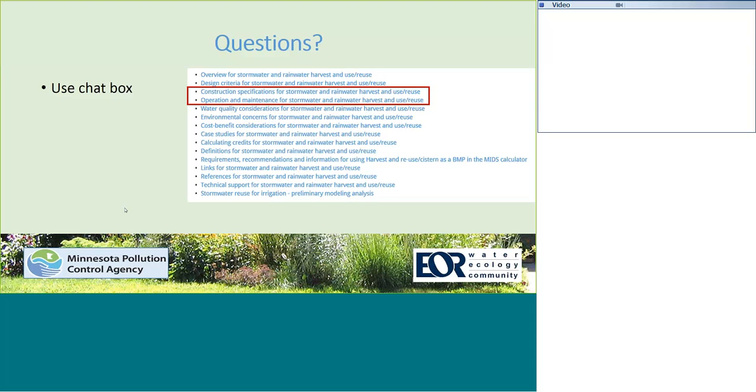Really, it is one of those iterative types of things here. Your source area is going to start to indicate what kind of water quality you have, and in many cases like sediment load or other things that are coming in. So once you look at different source areas, you could end up in very different types of design systems. If you're taking roof runoff, relatively low sediments, low pollutants, the rest of your design can be customized to that and potentially be a much more streamlined process.